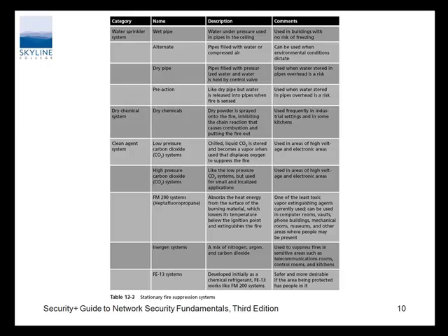Maybe what we used to use in the Navy on ships, you had sprinkler systems in all the magazines, obviously. So if anything happened in there, you would want to cool it quickly. And some of the sprinkler systems were wet and some of them were dry, depending on what that particular type of material called for. If you have magnesium, you certainly didn't want it in a place that, and you do have some of those because illumination shells, the primary thing is going to be magnesium. So if you get into things like that, you really got to think about what kind of fire suppressant you have in what areas.